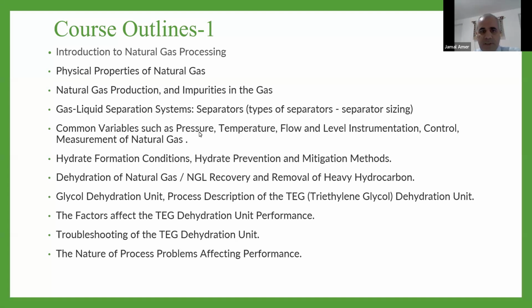Common variables such as pressure, temperature, and flow, level instrumentation, control, measurement of the natural gas. Hydrate formation conditions and hydrate prevention and mitigation methods. Dehydration of natural gas, NGL recovery and removal of heavy hydrocarbon.